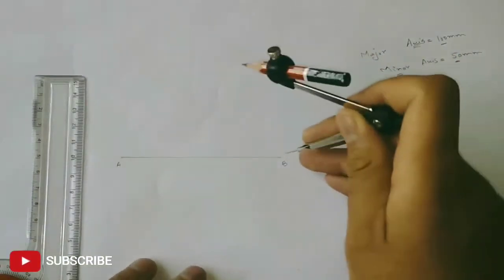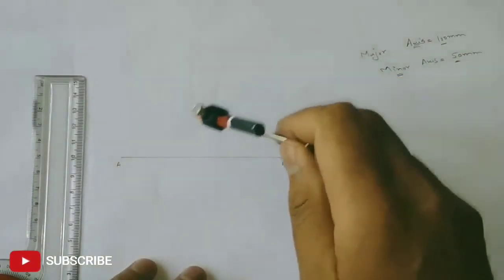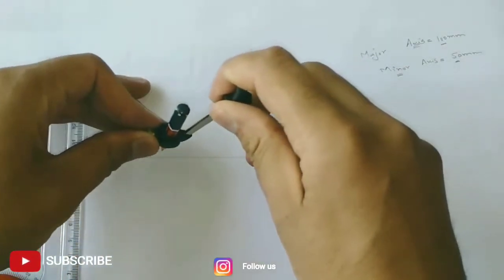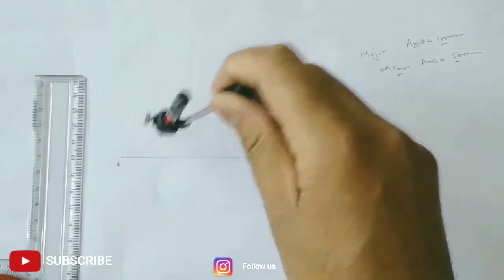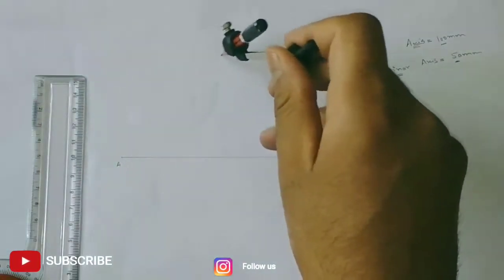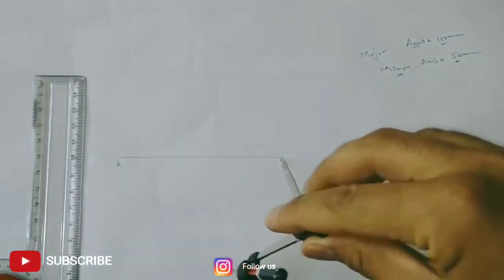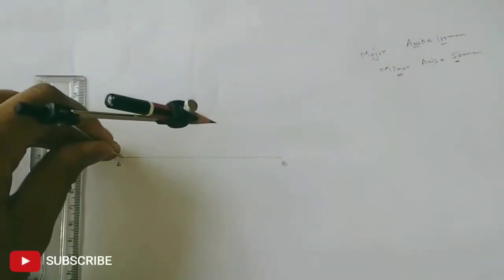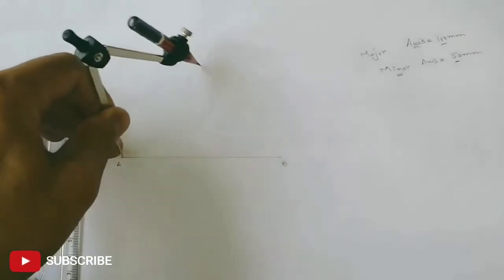Next, you need to draw a perpendicular bisector of this line. We know how to draw a perpendicular bisector. Open the compass a little less than the length AB and draw an arc in this direction and in this direction. Place your compass at point B and draw an arc in this direction and in this direction. But remember guys, these arcs should always be dim.